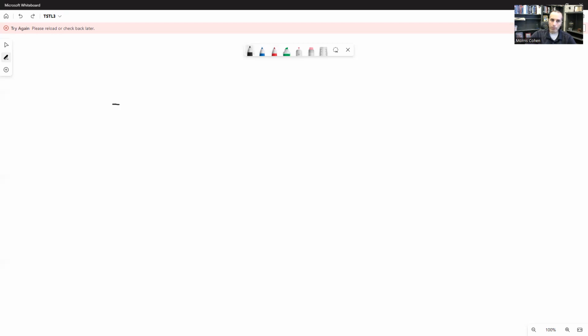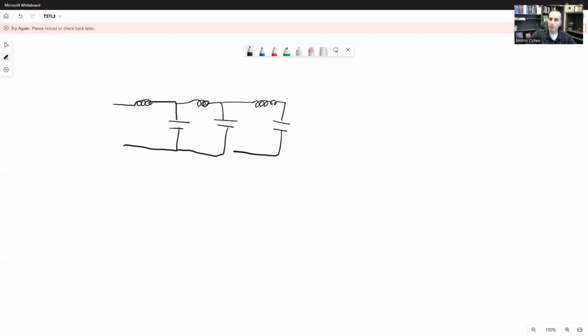And the model was, we've got an inductor and a capacitor in each branch. And this branch repeats over and over again. And so I'm going to draw this a few times so you can visualize. In a real transmission line, using actual inductors and capacitors, this is all shrunk down. Every segment is incredibly small, but every finite length of transmission line has an inductance and a capacitance associated with it. So this is an L and this is a C.